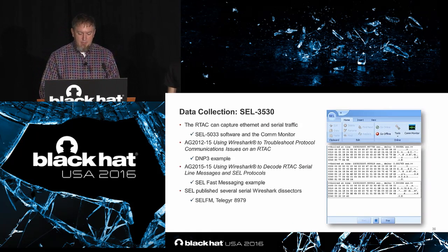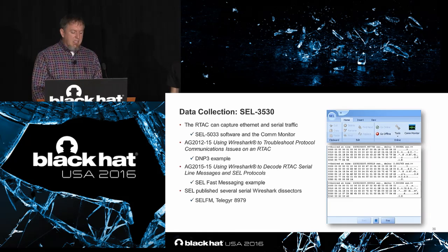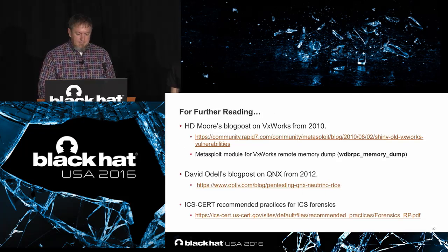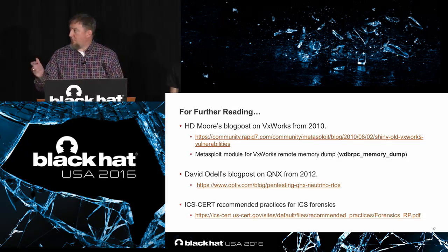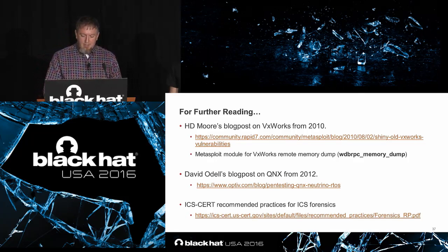You can also capture Wireshark Ethernet and serial traffic, and there are some good user guides from Schweitzer on this. And they also published several Wireshark dissectors for SEL Fast Message protocol, which is used by all their Schweitzer relays, and Telegyr 8979, which is a SCADA serial-only protocol that they can tunnel over TCP. For further reading, you might want to take pictures of these, and I'll also publish the slides.